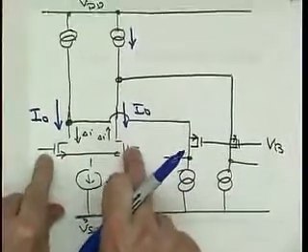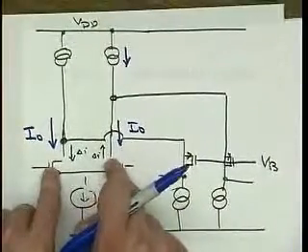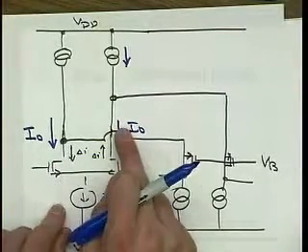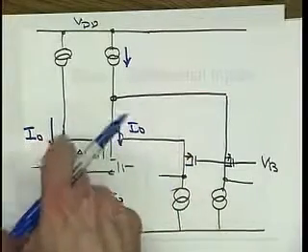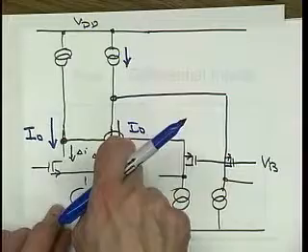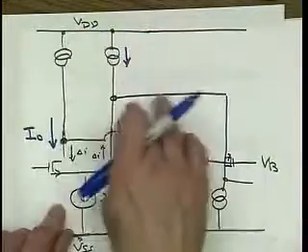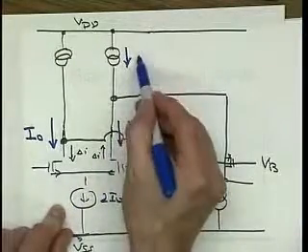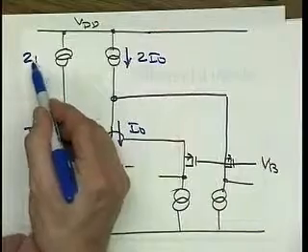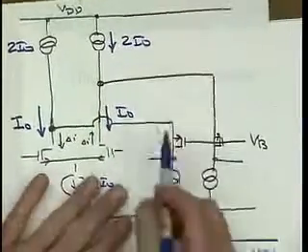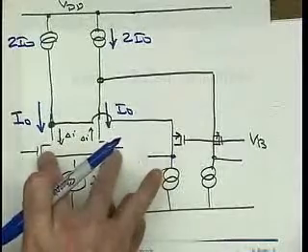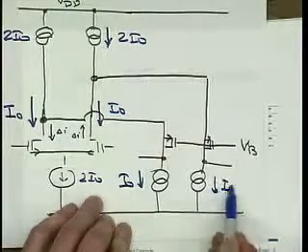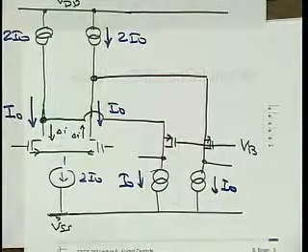Then the maximum change of current that I can produce in this diff pair is also just plus minus I0. If I completely imbalance this diff pair, then one current drops to 0 and the other one goes to 2 I0. Well, for these devices here to be able to mirror or fold a current of value up to 2 I0, the current that's flowing here needs to be at least 2 I0. Right? And then in the quiescent state, when this is balanced, I therefore get the current I0 and current I0 here also. Right? That's nominally how I bias these.